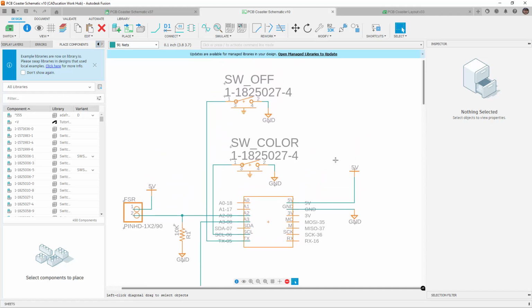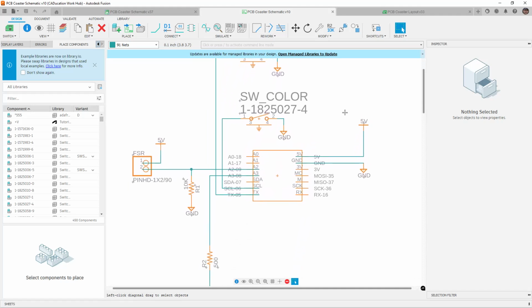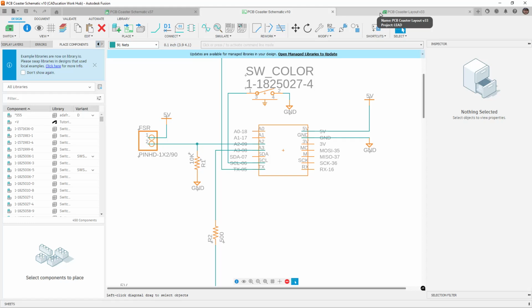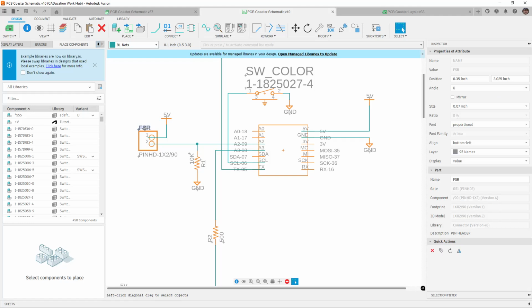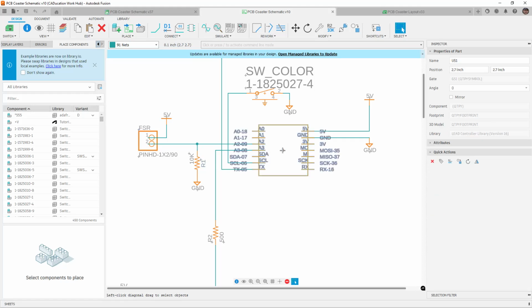Doing this at the schematic stage is going to give you all the information that lets you transfer and move over to the actual PCB layout itself. Keep in mind that all of the data associated with these components happens at the library symbol level. So each component will have things like silkscreen that's going to show up on the physical PCB, information like the resistor number or capacitor number, and information about the component itself.